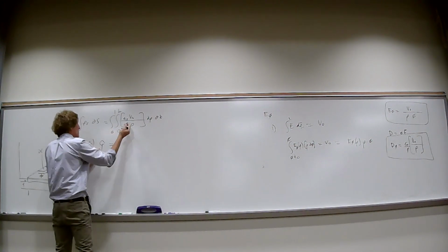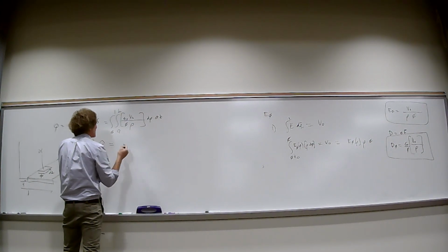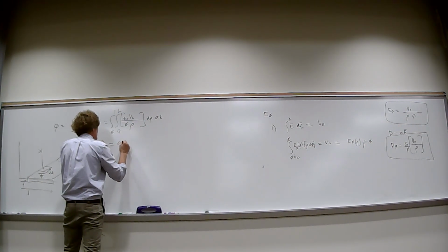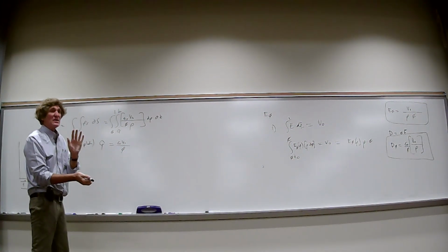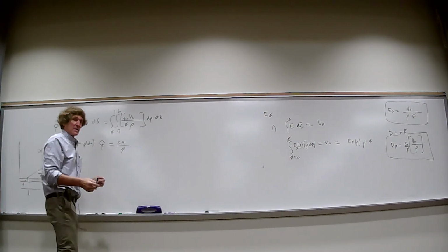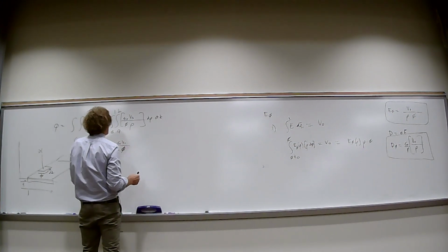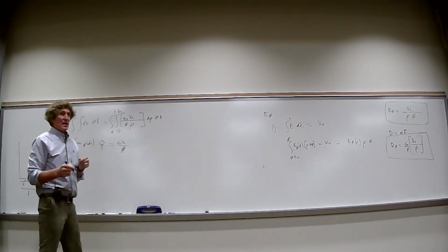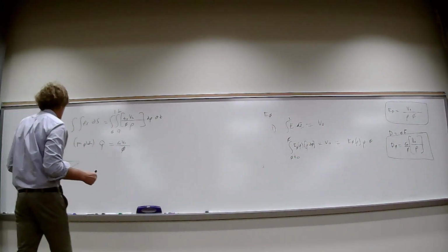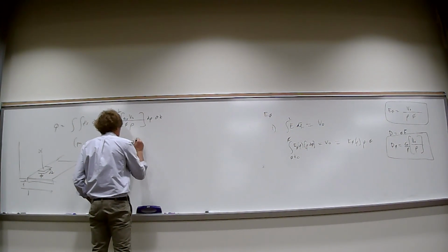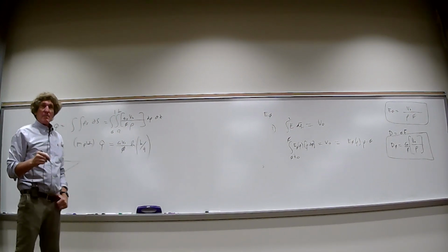So that means the total charge on one plate is going to be equal to, well, when I integrate dz from 0 to 1, I get 1, so I don't care about this. Then I take epsilon naught V naught out here. Phi is the actual angular difference. It's probably measured in radians, because I think it needs to be, but this is just the angular difference between the plates. And then when I integrate 1 over rho d rho, what do I get, class? Natural log of rho. You have to evaluate between the upper and lower. That's the charge. You all agree with that?